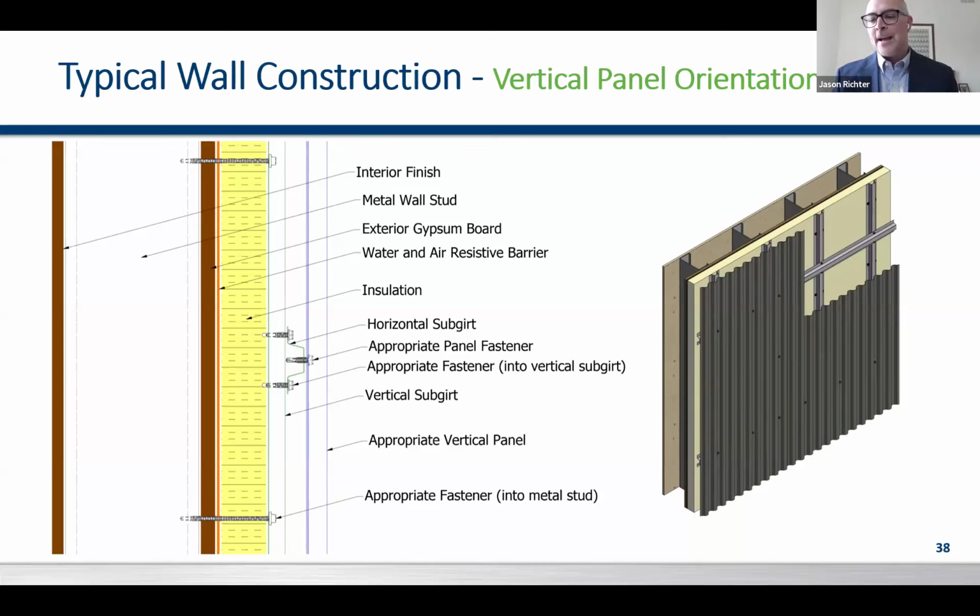I have seen it done where you will go with that horizontal member up against the insulation and they try and perforate the channels so that air and vapor, or water and vapor, can move throughout the airspace, but it really doesn't function as well as it should. And again, you're creating a shelf where moisture can sit and create some potential environmental issues with your wall assembly if you try and put that right up against your insulation.